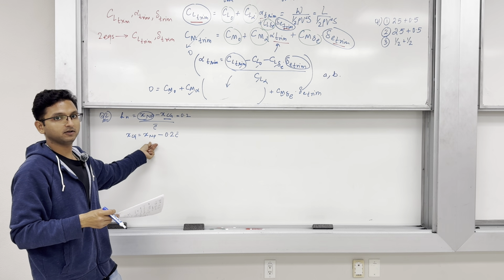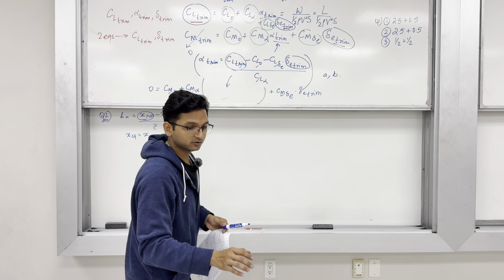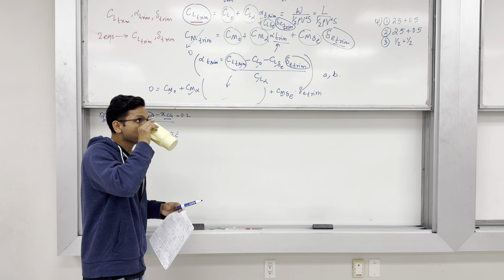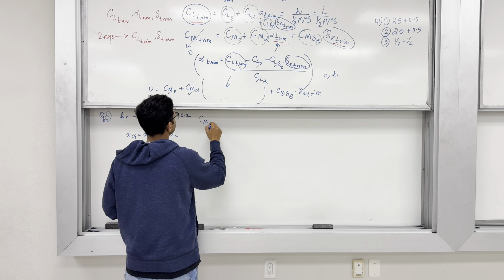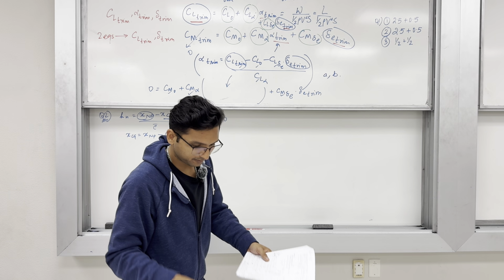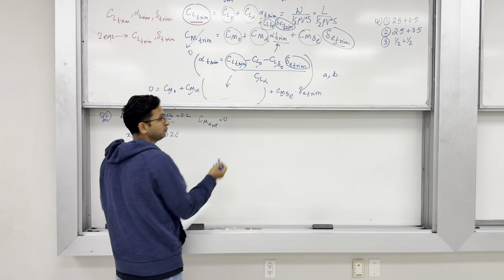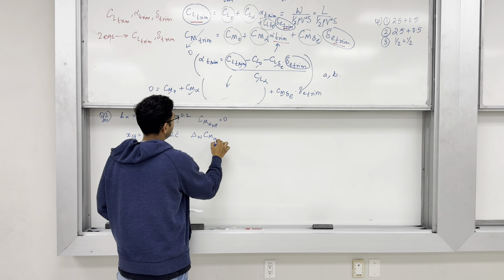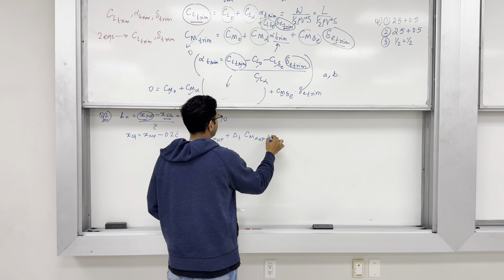And remember the definition of neutral point. Neutral point is the point about which the total moment about the aircraft does not change, which means that the constant part may be non-zero, but C m alpha about the neutral point is going to be 0, right. So, even if you did not have the equations for contributions, since the fuselage contribution is to be neglected, the contribution of the wing to C m alpha about the neutral point plus the contribution of the tail to C m alpha about the neutral point must be 0.